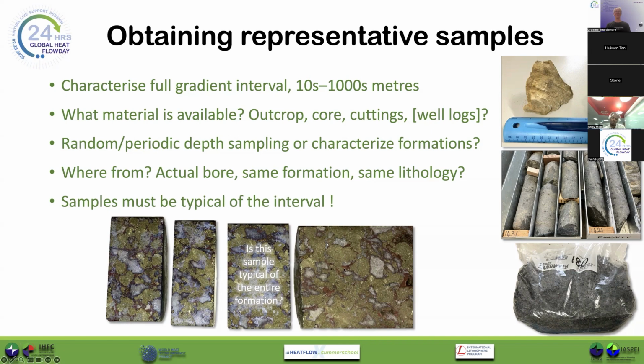Obviously, if a bore has been drilled specifically to sample a mineralized zone, and that mineralized zone is just a small component of a much larger unmineralized formation, then it's very unlikely that these mineralized samples are going to characterize that larger unmineralized formation. So we do need to be thinking about that.